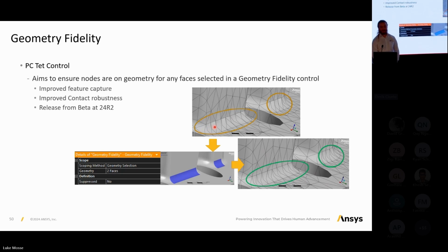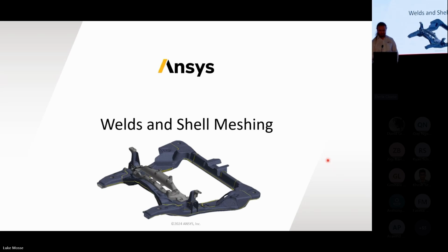Meshing TET elements on a round. These are kind of dodgy elements, and we wouldn't want those. So we can apply a face meshing to them now and onto these faces, and the patch conforming TET mesher will give us a much better quality TET mesh around there.